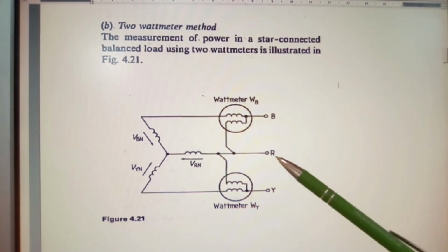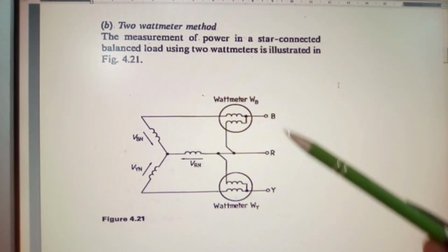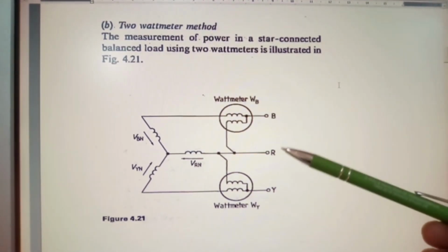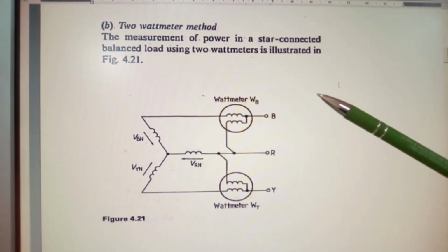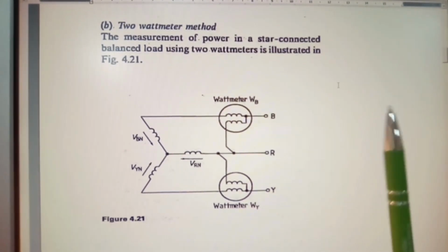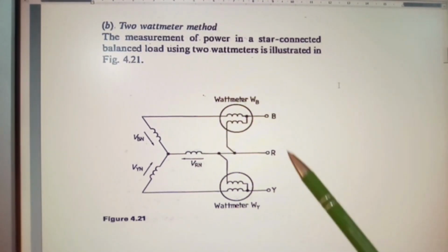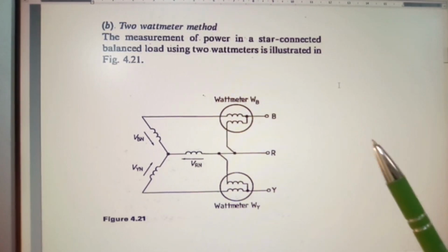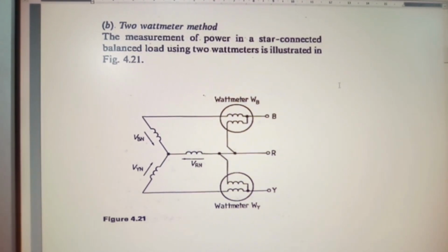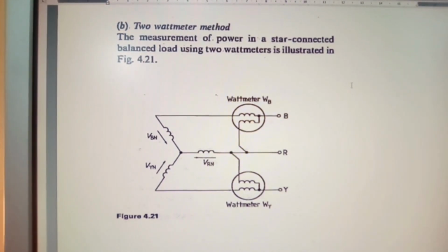And please note that we're using here system red, yellow, blue, but this is no longer the color for the three-phase system. So please make sure you apply the up-to-date references in regards to red, yellow, blue. I believe they're now black, gray, something or the other. It is important for you to look up and make sure that you're using the correct references in regards to our phasing. Know your phase colors because it's applicable in the UK and it is in Europe. I don't think they will change, irrespective of us leaving the European Union.